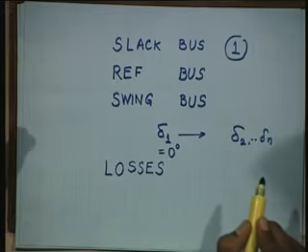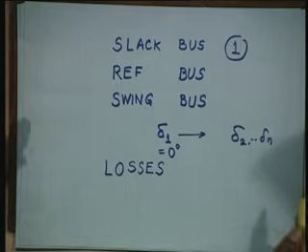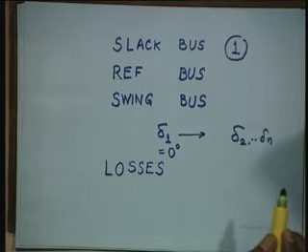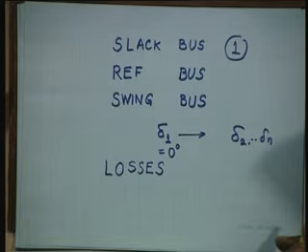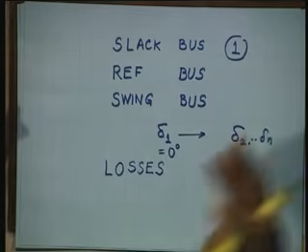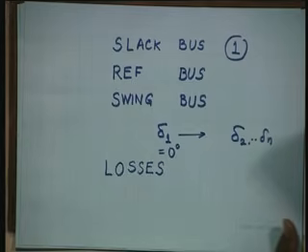If you have a state like UP and you have a Singrauli power plant which is not located in the middle of the UP, it doesn't mean you will not have a slack bus as Singrauli super thermal power station. But it is always better to locate it centrally so that the distance traveled to feed that power is minimum. Less the distance, less will be the losses.